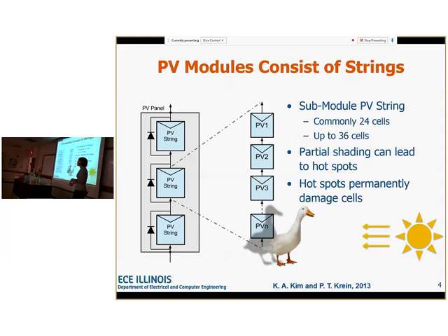And he flies down, and he's just sitting right in front of your panel. And little does he know, he's causing a shadow on your panel. He's just chilling. So what happens here, though, is this one shaded PV is not getting as much light as the other ones, right? So it's like a weak cell. It can't produce as much.